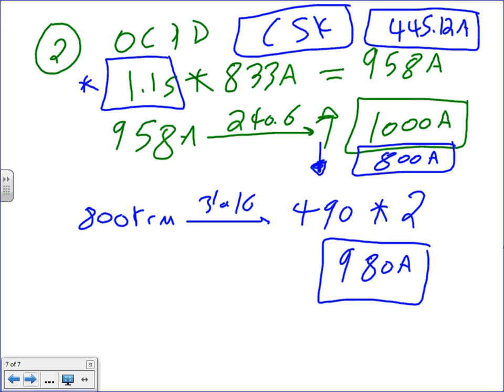But we size based on the overcurrent protection device and the conductor. The reason is that the generator has its own overload protection from the manufacturer. This circuit breaker is not there to protect the generator. Generators have overvoltage, undervoltage, and tons of protection right in the generator's control. I'm not worried about the generator, I'm worried about my conductors.